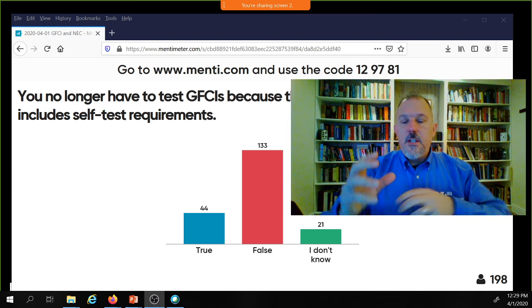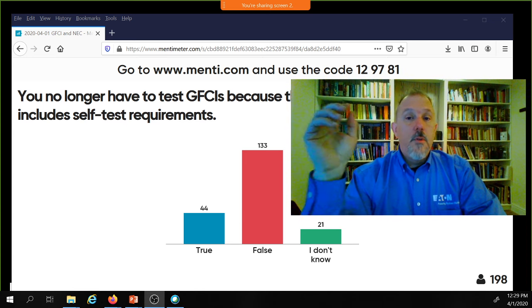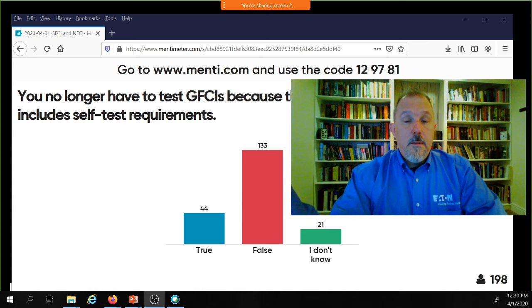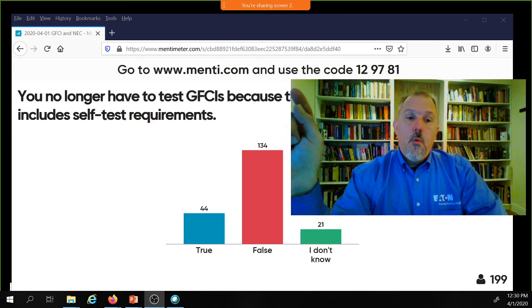The self-test feature, if it finds a problem, and I think all manufacturers implement the requirements in the standard this way, will find a problem, and then when you press the test button, the device will trip, but it won't be able to reclose. So it won't just open on its own. You could design it that way, but 9 times out of 10, you probably wouldn't want that to happen.